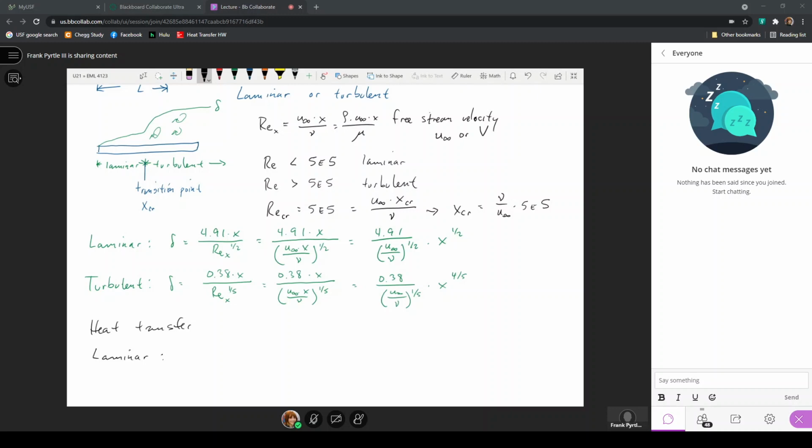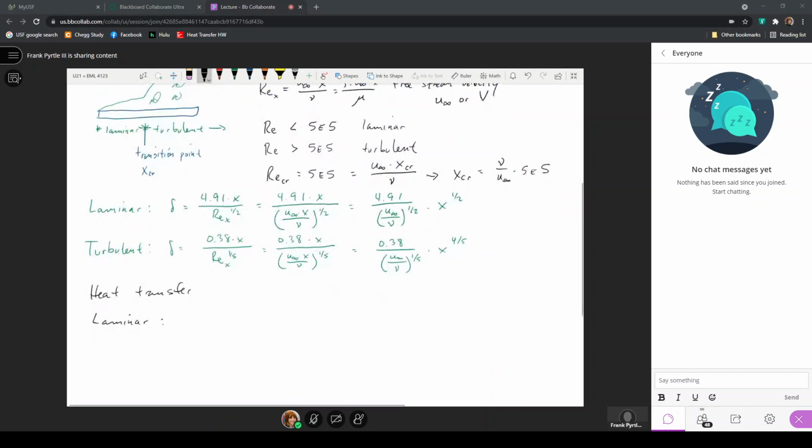And multiplied by that temperature difference is that heat transfer coefficient, so that we can write expressions for the heat flux in terms of the heat transfer coefficient and the temperature difference that occurs. So here the heat flux by convection is just h times Ts minus T infinity.